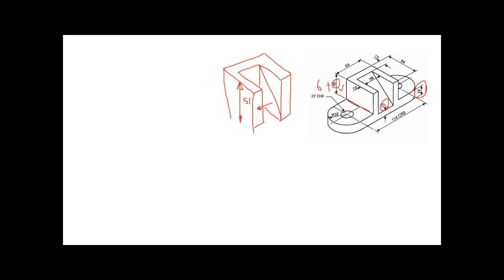And see, guys, if you said 51, you'll be in trouble after that. Why? If you draw the base at 51 in two dimensions like this, and then make another depth, which is supposed to be 19, you'll be in big trouble, because this distance is not 51. If you look carefully, this distance is 45. Is there an easier way, guys? Yes. We need to draw the base first.